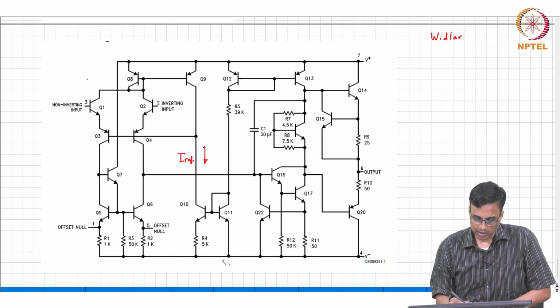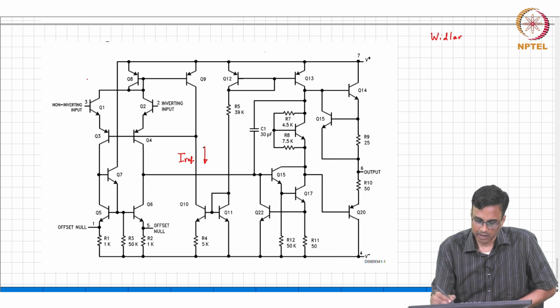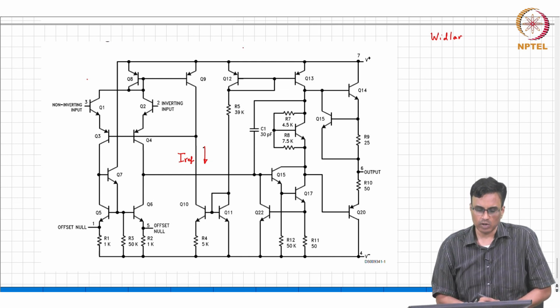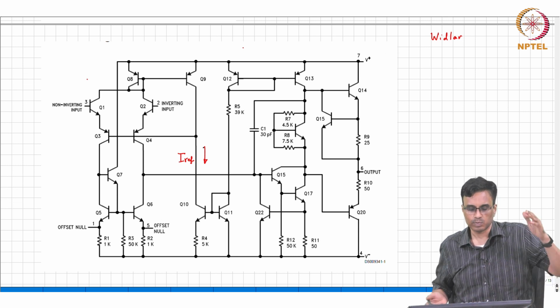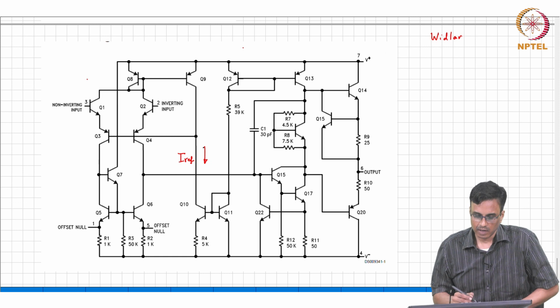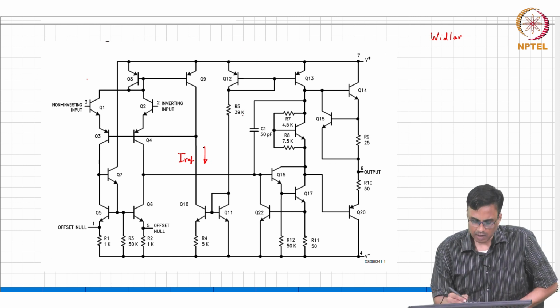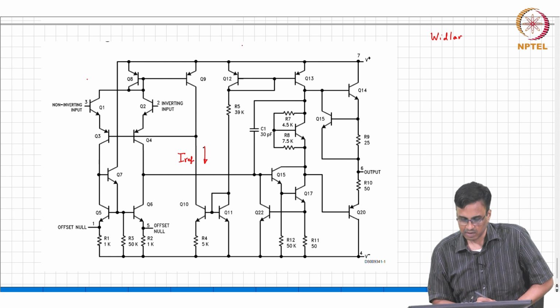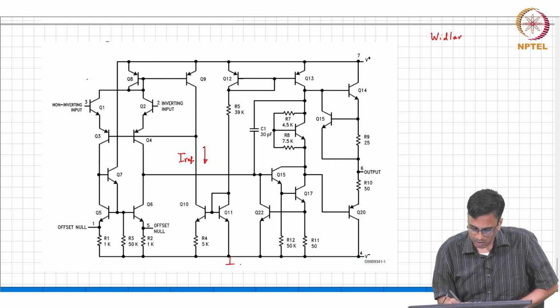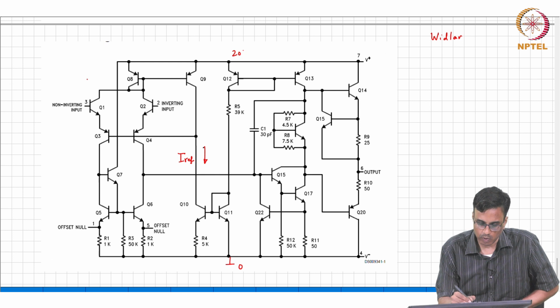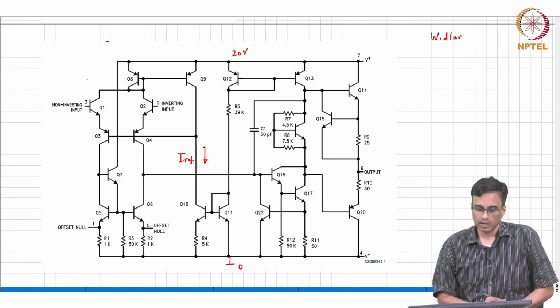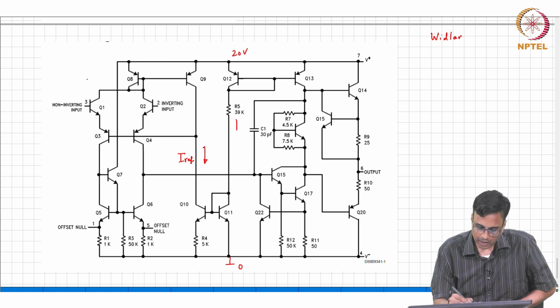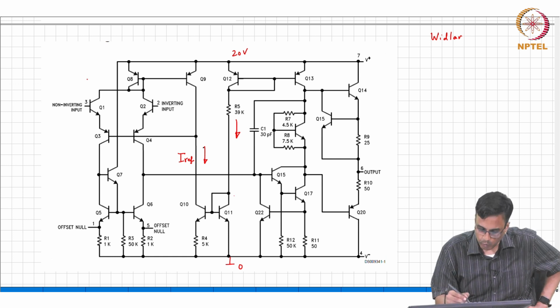So let's first assume that these op amps are intended for dual supply, right. I mean people use plus minus 15 volts and so on. But it does not matter. Let us just, for simplicity, assume that this is 0 and this is, I do not know, some 20 volts. Okay. So, what comment can you make about the current through this R5? What is this voltage?